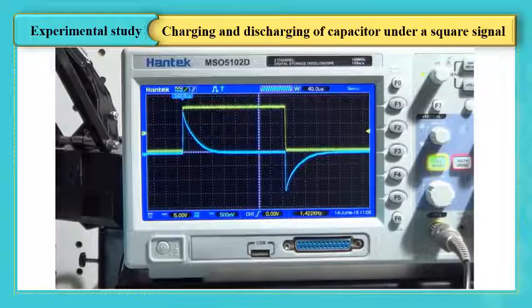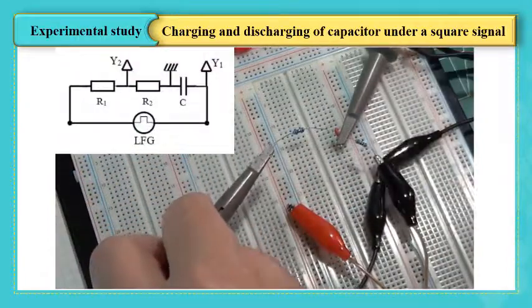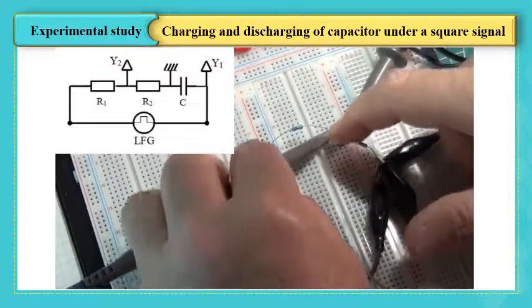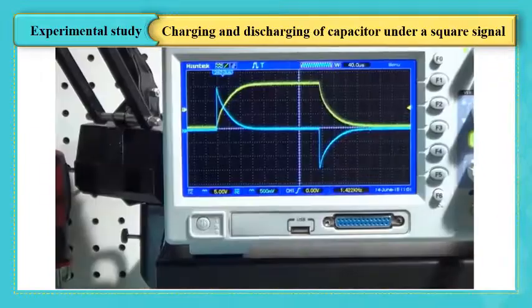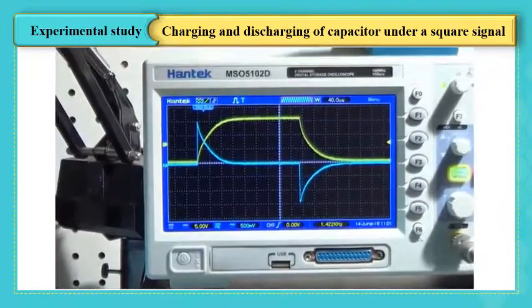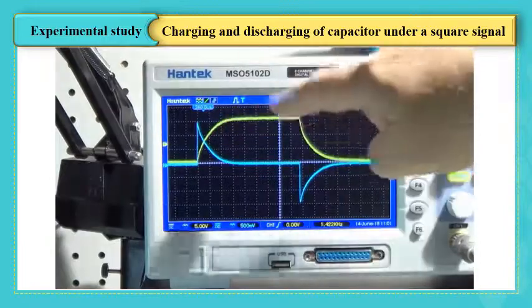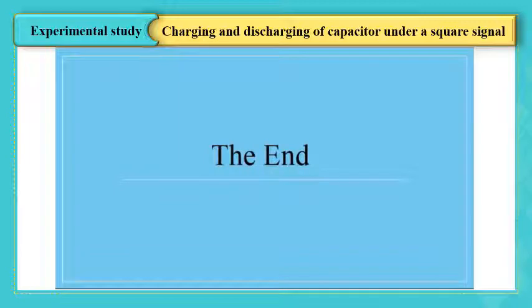Let's compare now directly the voltage of the capacitor and the current of the capacitor. The channel where I measure the voltage from the generator directly onto the capacitor. Let's go back and see what happened here now. See, now the yellow line is the one that represents the voltage across the capacitor. The blue line is the one that represents the current across the capacitor.